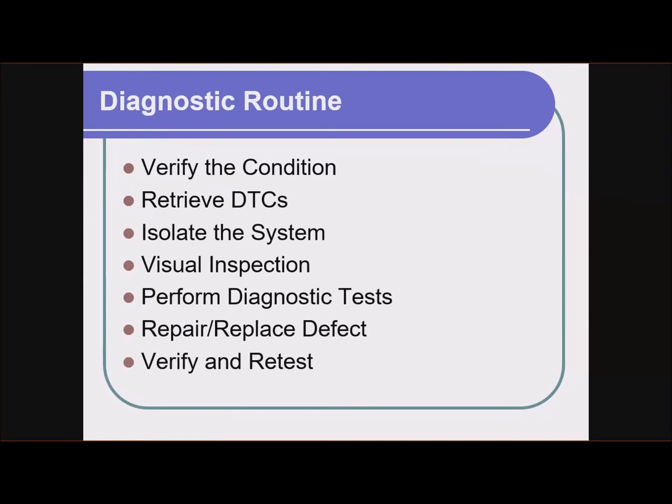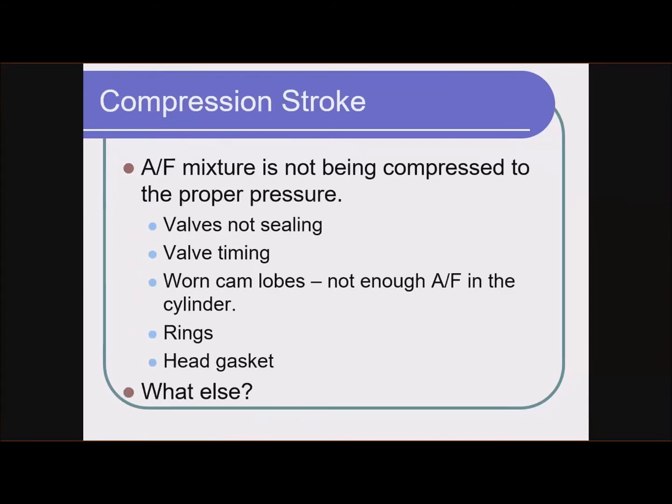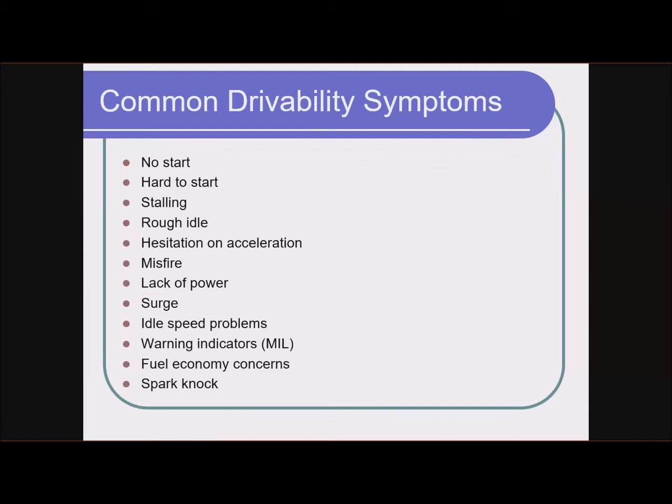We have a drivability symptom, right? There was this whole list of symptoms here. Customer comes in and presents us with one of these symptoms. And believe me, they're not necessarily going to use the correct terminology. They just might come in and say it runs bad, right? So it becomes your problem then to convert what they're saying to fit one of these actual symptoms. So they might say it runs bad. Well, you might find out that that's misfire, or you might find out that it's a rough idle.